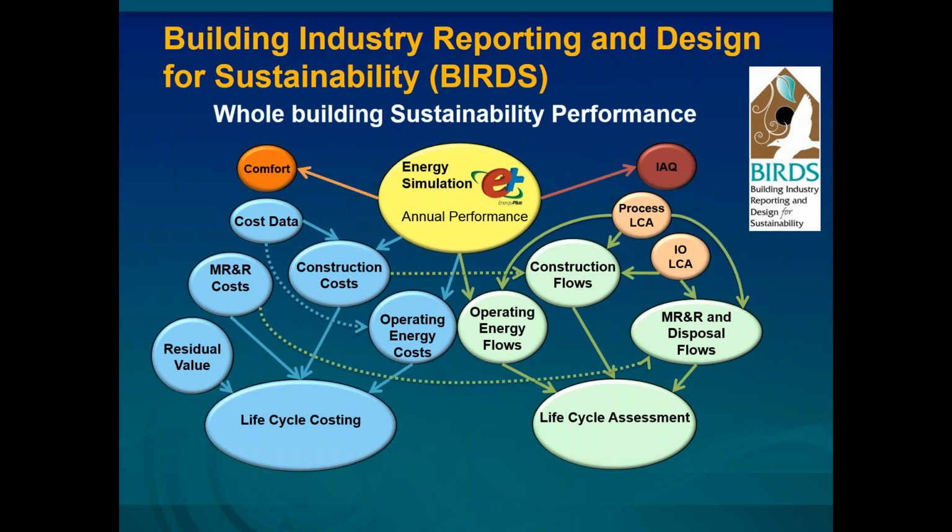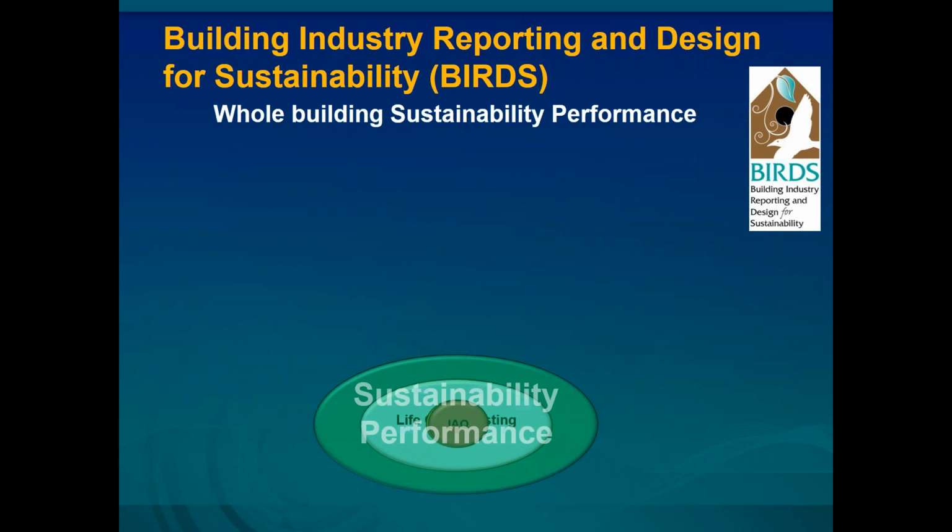And then I mentioned a concern about the indoor environmental quality at this point for one of the databases, which the demo I'll give will include. It is two different indoor environmental quality metrics. One is thermal comfort, so whether the occupants are comfortable, and then indoor air quality. So we have a proxy for that I'll get into later. So by combining these four aspects, we're able to calculate sustainability performance for a whole building over its life cycle, based on the changes in energy efficiency that are being considered.